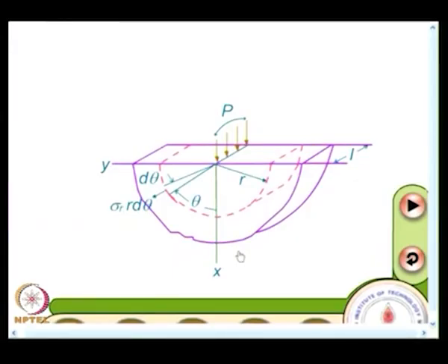And if you look at the concentrated load, this is like your Boussinesq problem. Then you have extension of this. If you look at the contact stress analysis, it all started from this basic solution of Boussinesq, which is extended by Hertz, and you have Hertzian contact problem. And we have also looked at how to find the solution for a disk under diametrical compression. That also comes from this basic solution. From this as the basic solution, you could find the solution for the case of a disk under diametrical compression. So, it is a very useful solution,